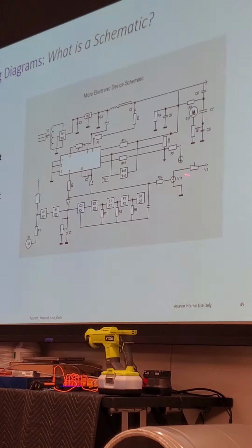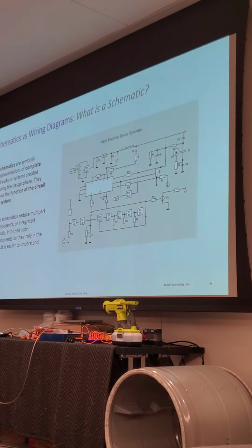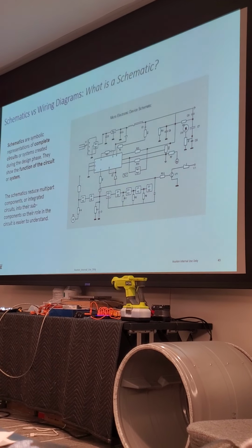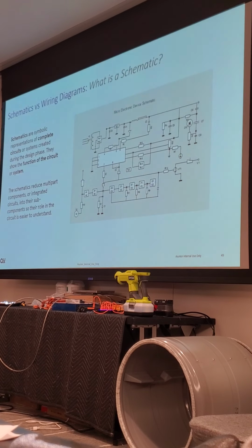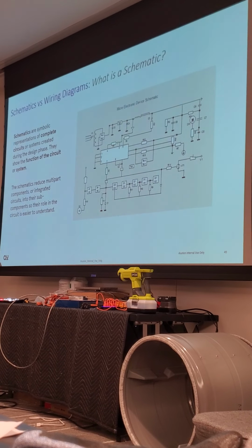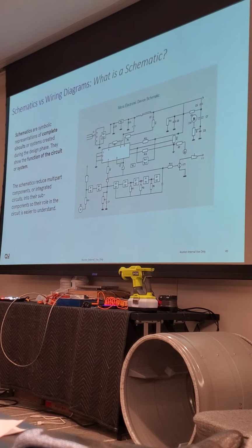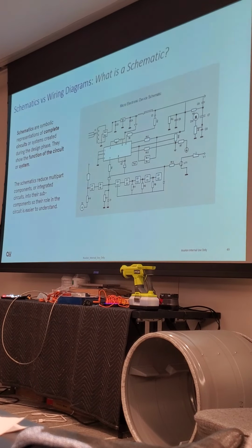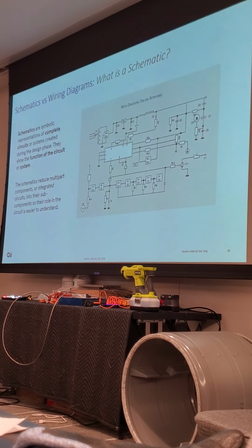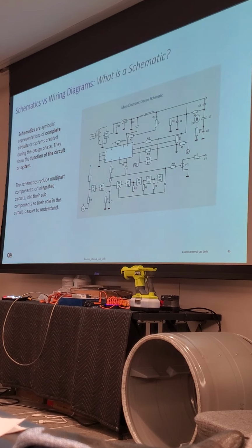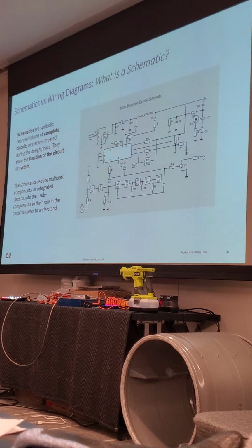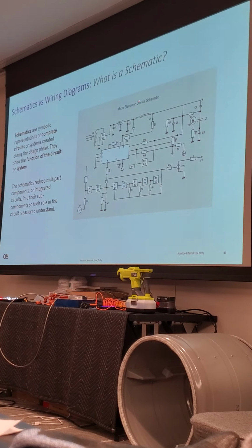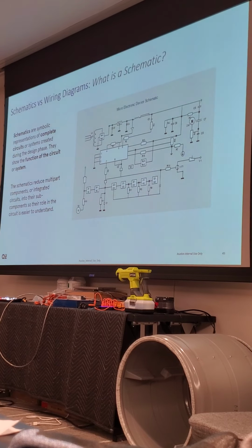I thought the triac was the 2 triangles next to each other. They can be, but there's also a different type here. There's the triac on the board, and then the triac that's separate, because some triacs can actually sit in the bottom of the microwave, on countertop microwaves, to split that signal back and forth. What did a triac do again? They send power to one source or another as it needs. What about that top triangle that has no line to it? This one right up here, that's a diode.